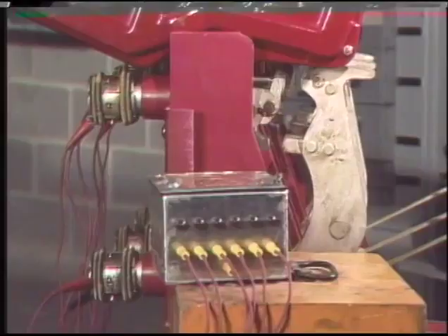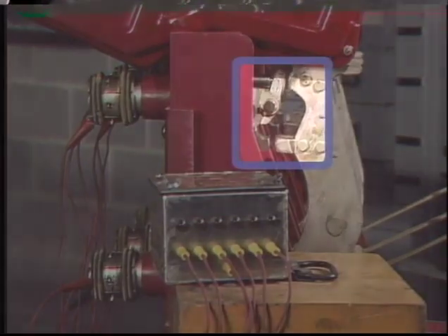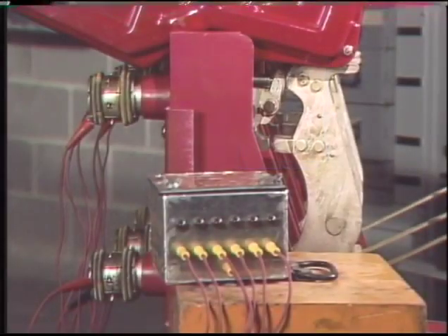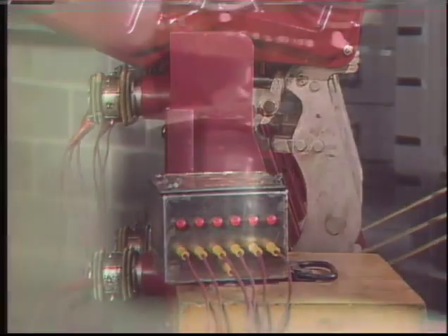After a breaker has been cleaned and inspected, the contact adjustments can be checked. We'll look at contact adjustments in detail later, but in general, there are 3 basic contact adjustment checks. One of these is initial contact engagement, which means that when the breaker is closing, the arcing contacts should touch at about the same time. A second contact adjustment check is for contact alignment, which means that the contacts should line up with each other as they are designed to.